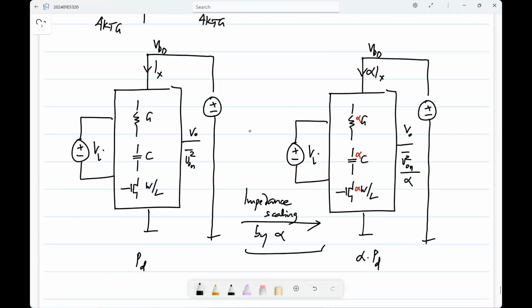And you can also use it in other ways because you have a circuit, it's usually some complex circuit with many other sub-circuits and so on. Now you can see maybe it is dissipating too much power, and then you can take some part of the circuit, you look at its noise contribution, maybe it is very low. Then you can afford to increase its noise contribution without changing the overall noise too much. What will happen then?